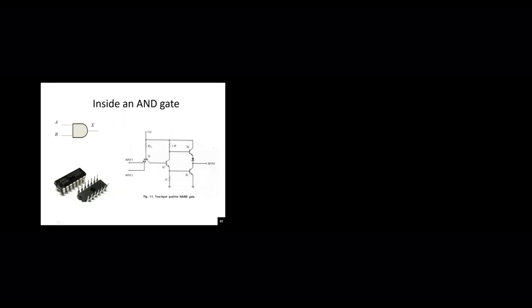And here's an example of a NOT gate, but this time using CMOS logic. So remember back on Tuesday I said the range of voltages that's considered as a 1 versus a 0 depends a little bit on the type of logic circuit that you're using. Well, the 2 types are a TTL circuit or a CMOS circuit. And it just basically means inside that gate, even though to you when you buy the chip it doesn't look any different, the elements that are used to create that logic are slightly different. They're using transistors or they're using CMOS logic.